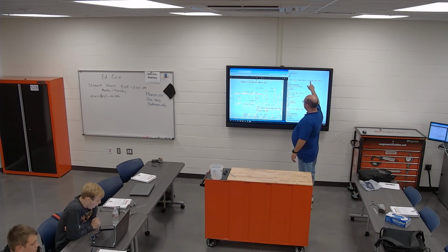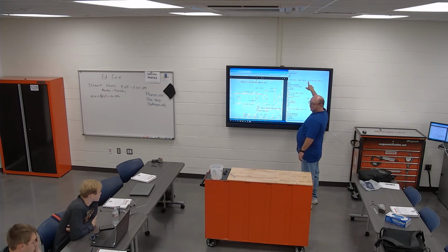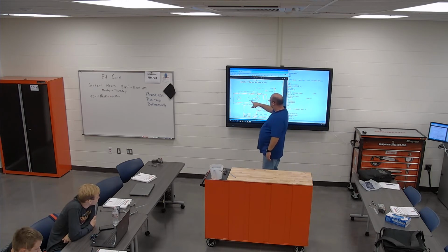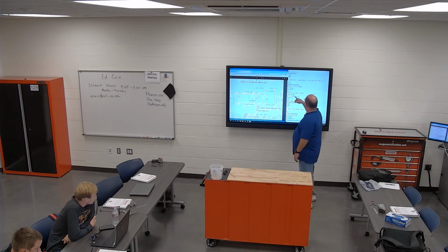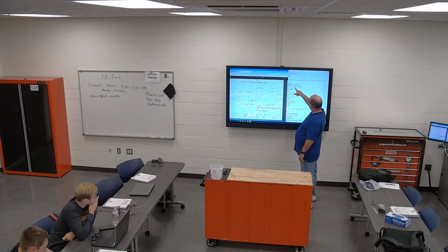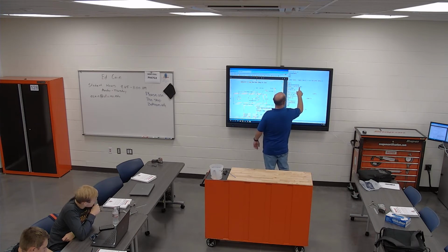So your spot drill, we're going to spot drill 3 holes. We made it the next tool, tool 3, and I used the 750 spot drill because I want to put a little chamfer on this hole, a little chamfer on this hole, and I think we might have even done a little one on that hole. So M6, T3, same thing as before, G54, and then we go to the position of our first hole, which is negative X and a Y of, which would be this one. Because if you look, this hole's not on center line, it says that's 938, and this is 2 inches.